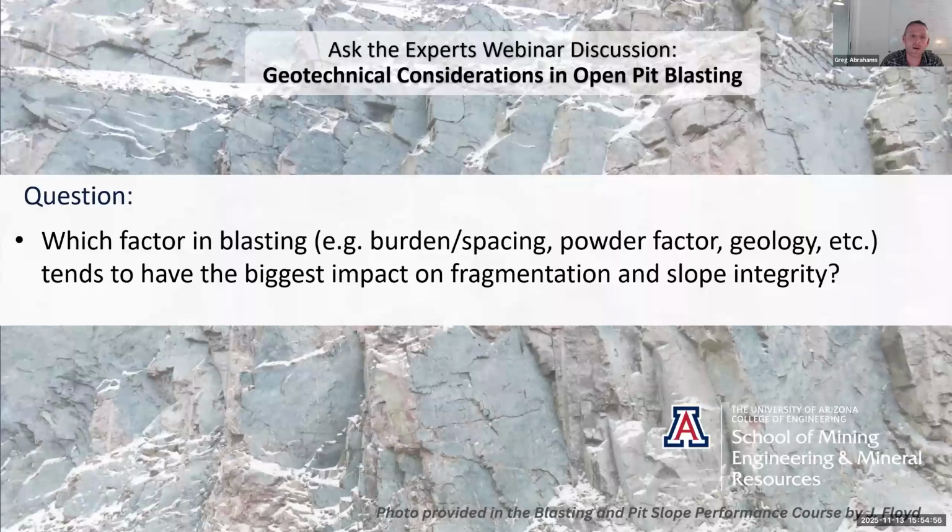And then moving on to the slope integrity, well, that might depend. Are we talking about the near field or the far field? Are we talking about a scenario where we're double benching and triple benching and we want to have a beautiful face and we don't want any crest loss because it's a rockfall issue?